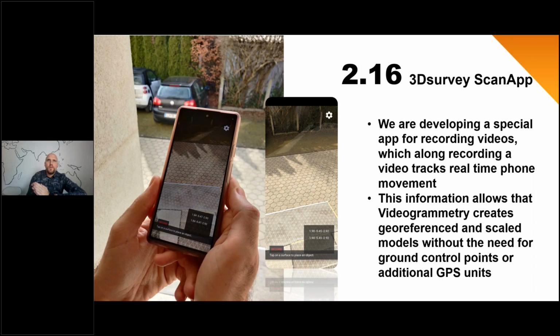So today we saw basically two approaches to use photogrammetry. For the first approach, we used some ground control points to orient the data. And for the second one, we just oriented the data manually, rotating the model so that it would fit some data, and then we have the model correctly scaled and positioned. Now, of course, we want to do more than just that.